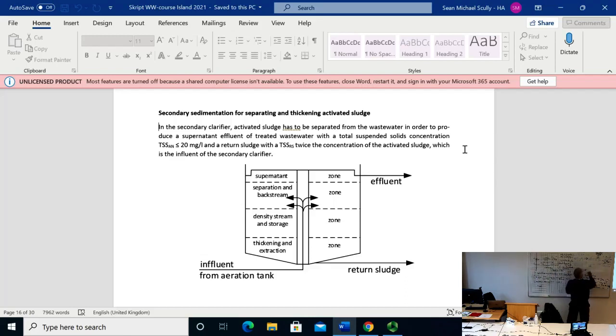Now, what I really want to show you is when we have here 100 liters per population equivalent, then we have here 75 liters per person equivalent per day. So at this point, we have 175 liters per PE and day. Simpler than I thought. This is the inflow which we have here. And the effluent will be our 99.7, no? Or the 100 really, no?